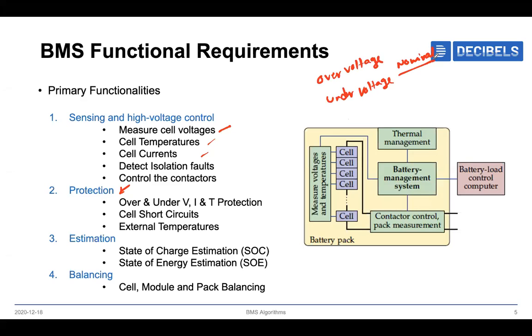So this nominal voltage will be used mainly for determining the battery pack size, so that we are on the safe side, when we are in the limits of under voltage, or reaching over discharge. So in order to be on the safe side, we'll go with nominal voltage when deciding on the battery pack size. But when we are discharging or charging the cell, we'll make sure that the cell is operating between these two limits, the over voltage limit and the under voltage limit.